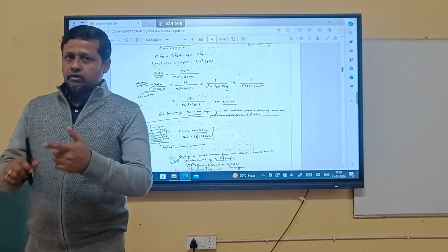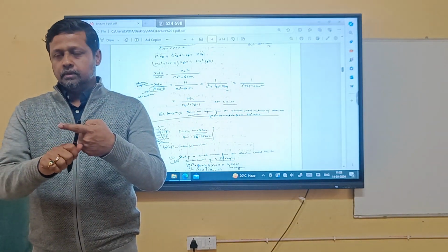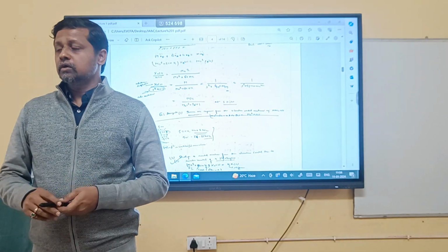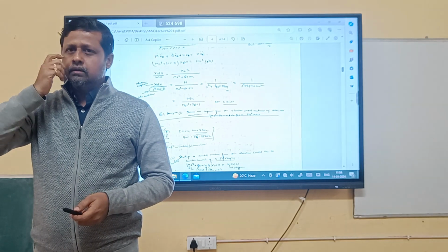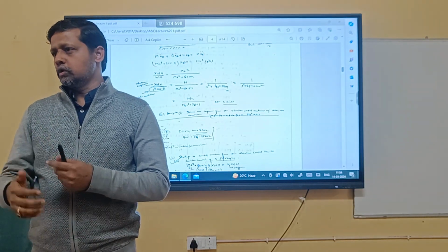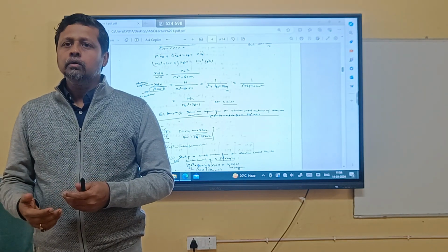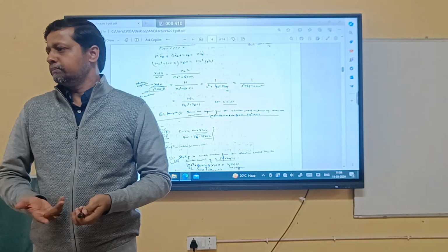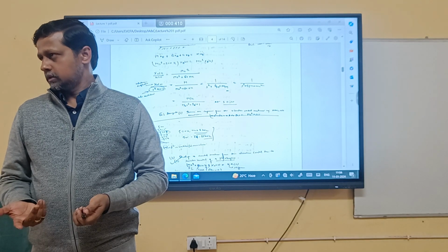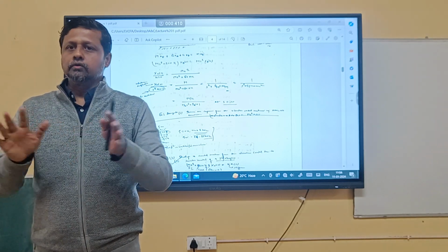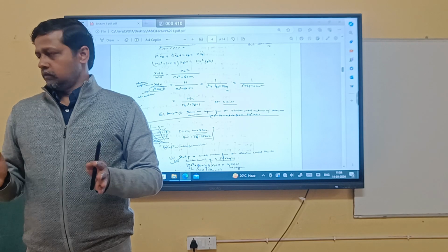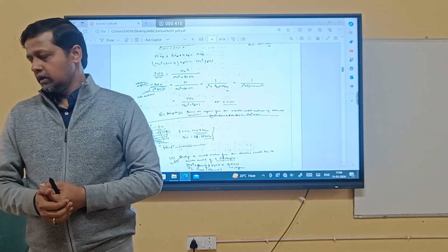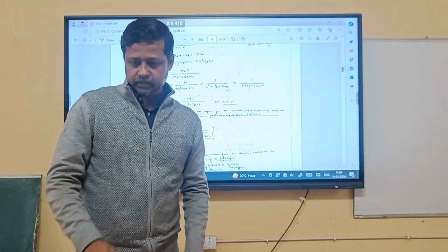Done. So now natural frequency is known. Zeta is known. If there is some miscalculation, you see that zeta is fine, but it's not perfect. There could be some improvement. Then what will you do? Redesign. Because you need to ultimately change the values of m, k and b. Once you get the satisfactory zone, you fix it. Once you fix it, then you can go for mass production. So we will continue this discussion in the next class.